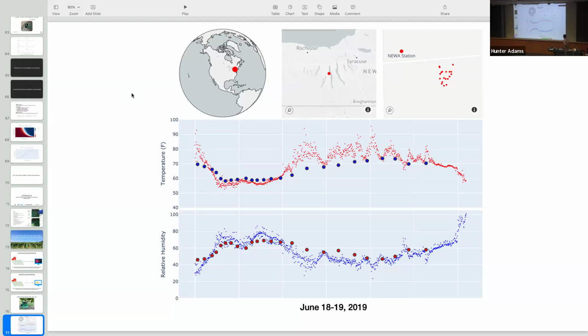This indicated another problem too, by the way. This was a partially cloudy day. The clouds were coming in and out of the sunshine. It was sort of sunny and cloudy. And what you could see is that when the sun was out, I was getting artificially high temperature readings. The sun was actually warming the board, right, which made for an artificially high temperature reading.